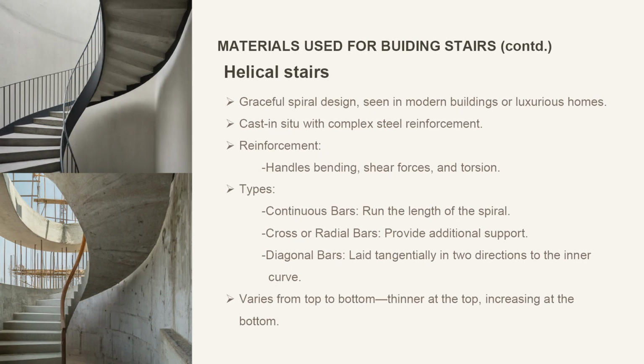Now, for a touch of architectural elegance, consider helical stairs, which is the next choice. Helical stairs are those graceful spiral designs you might see in modern buildings or luxurious homes. These stairs are cast in situ, meaning they are formed on site with a complex arrangement of steel reinforcement to handle bending, shear force and torsion. The thickness of the RCC slab varies along its spiral shape, adding both strength and stability.